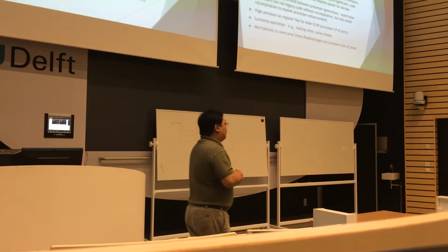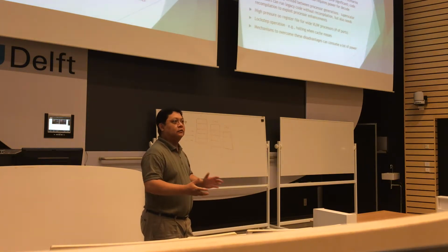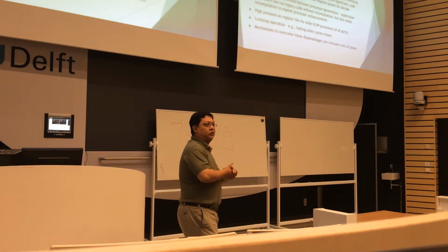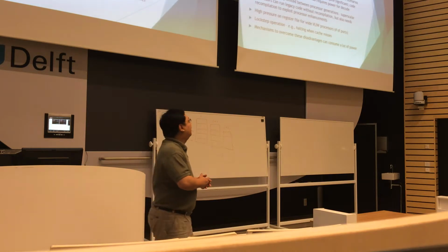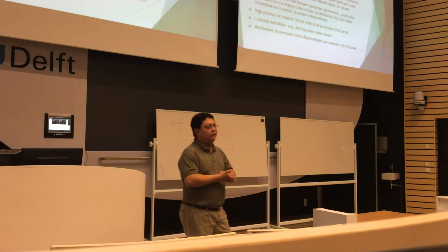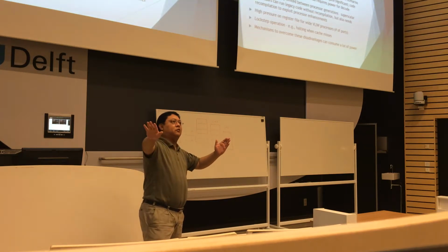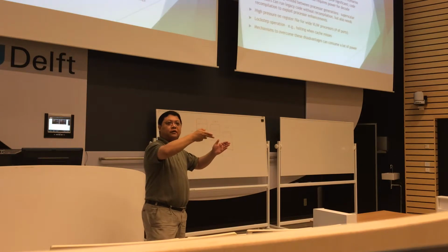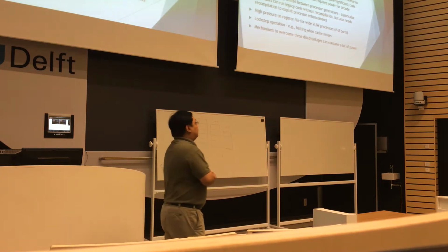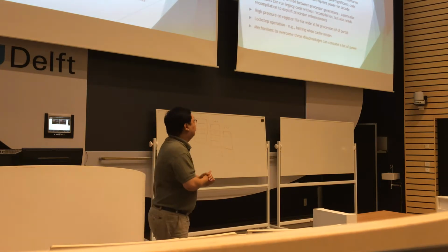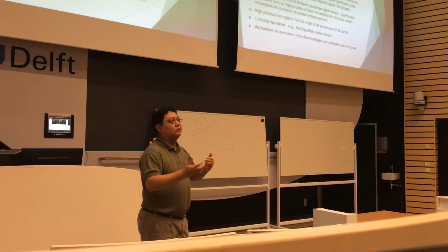Now, of course, if NOPs are so common, they will find ways to reduce the code size. One way to do it is simple compression. You say, oh, there are so many NOPs, and you find smart ways to not store them. There are different ways to do that, simple encoding, but you can also have things like stop bits. So you say, my instruction word only has 2 operations, then I put a stop bit here, which means the rest are NOPs. If the rest are NOPs, I don't need to store them because there's a stop bit there. So when you decode it, stop bit, go to the next word. The next is the next word. So there are many different ways to deal with this problem. Now, if you don't deal with it, another thing is that you have to store them somewhere at some point.